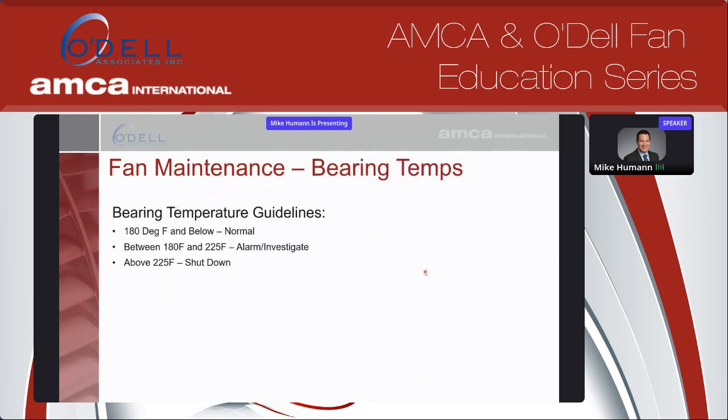So when we talk about bearing temperature, that's certainly something you want to have a guideline for. Most fans run between 140 to 160 degrees Fahrenheit, that's about 40 degrees C to 55 or 60 degrees C, and that's normal. Anything below 180, even slightly above that, is pretty normal.